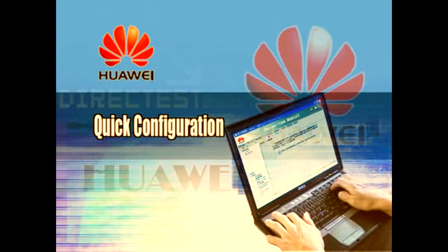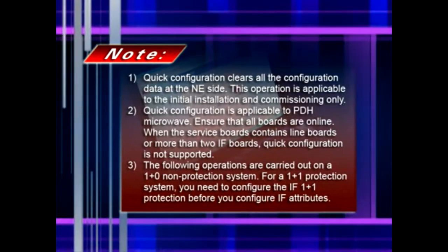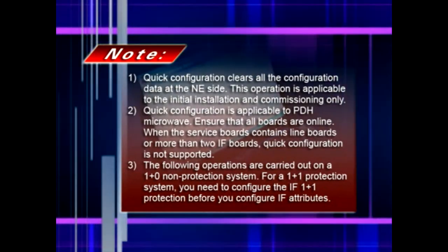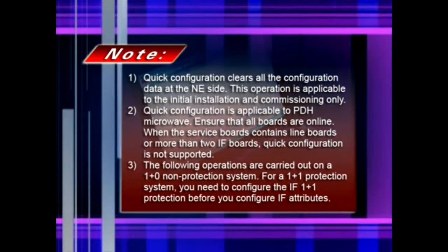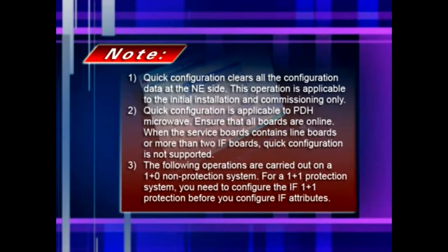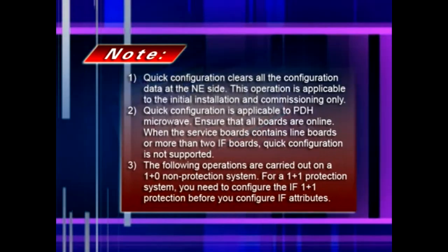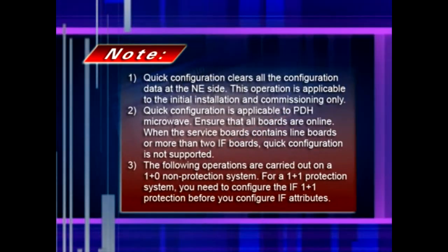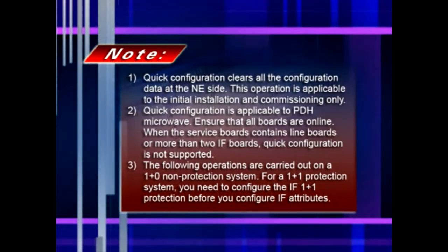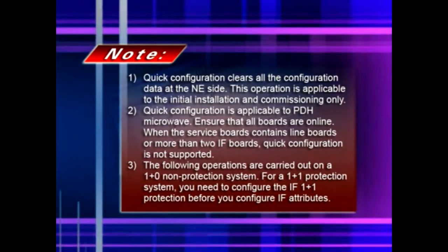3. Quick configuration. Note: 1. Quick configuration clears all the configuration data at the NE side. This operation is applicable to the initial installation and commissioning only. 2. Quick configuration is applicable to PDH microwave. Ensure that all boards are online. When the service board contains line boards or more than 2 IF boards, quick configuration is not supported. 3. The following operations are carried out on a 1+0 non-protection system. For a 1+1 protection system, you need to configure the IF 1+1 protection before you configure IF attributes.